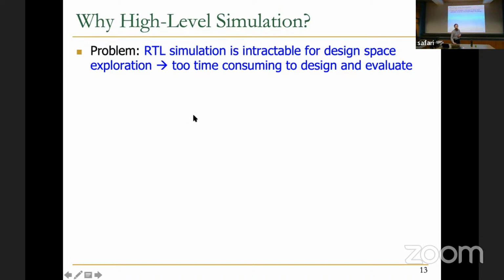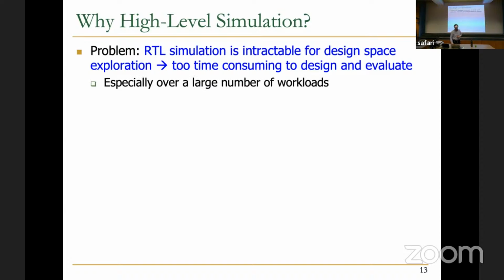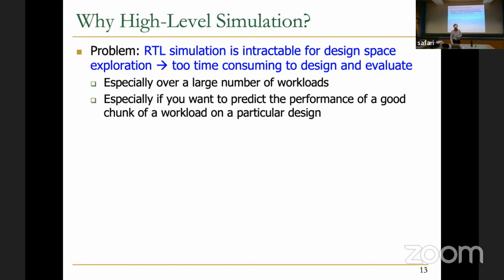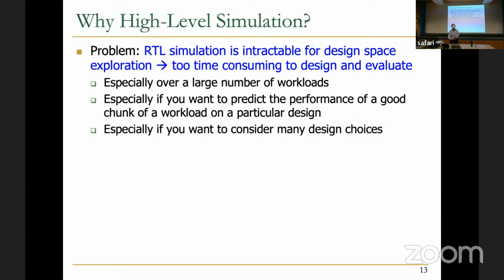And the main issue with RTL simulation or low-level simulation, which is done with Verilog, is that it's intractable for design space exploration. It's too time-consuming to design and evaluate if you have a simulator at the gate level, especially over a large number of workloads. Especially if you want to predict the performance of a good chunk of a workload on a particular design. That basically becomes intractable. It takes years, let's say. And especially if you want to consider many design choices. So you want something much faster.